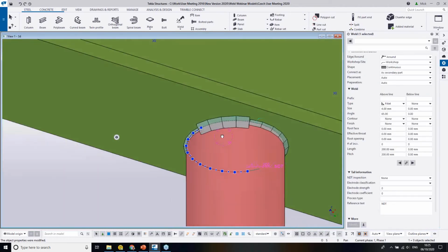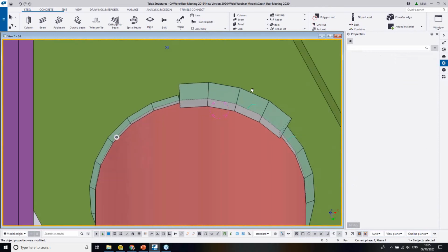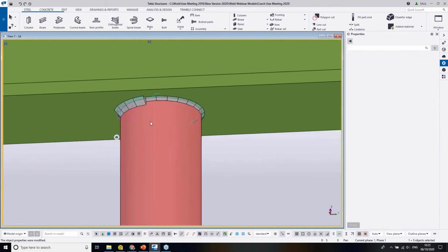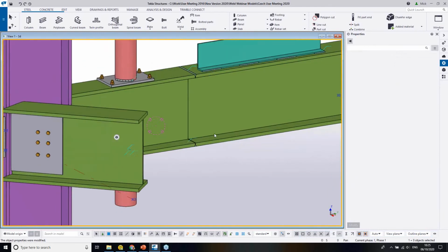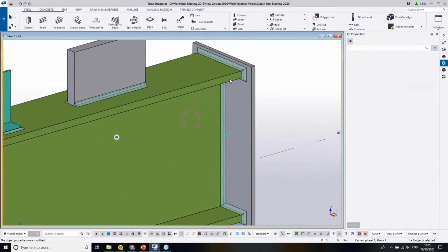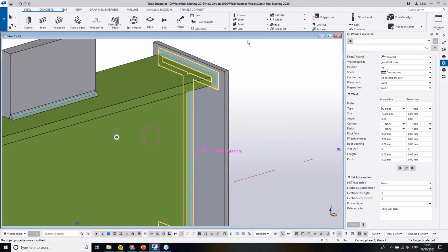So that allows you then to have different parts split of these welds around these pipes. Seems very odd to do that, but you'll see that in multiple locations. And I'll give you another example of splitting these welds. Here, this is the one I put in earlier where I've got the weld all the way around. I use the typical weld command.